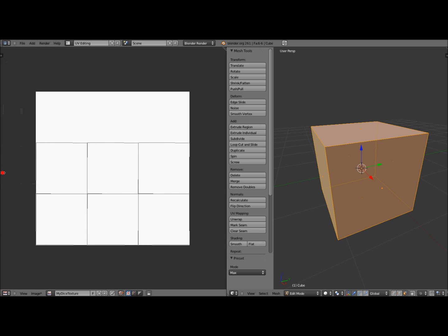Click the mouse in the center of the first UV face to paint the first face of the playing die. Paint the pits for the remaining faces of the die in the same way. Use the graphic shown here or a photo of a real playing die if you need help in painting the pits.